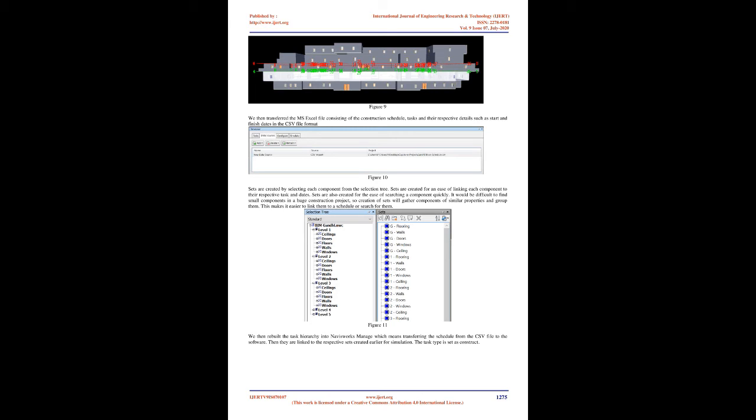Once the grid lines were made exactly according to the dimensions of the outer walls of the ground floor, we start to make a two-dimensional floor plan using the walls function. We draw the exact dimensions as mentioned in the floor plan and complete the floor plan for each floor by also maintaining the reference grid lines. These grid lines need to be maintained in order to get each floor aligned correctly as there is no structural component provided for our project. The grid lines act as a substituent to the points where the columns would come into existence in real life.